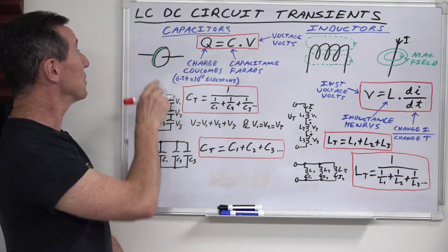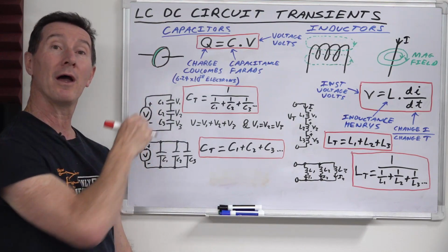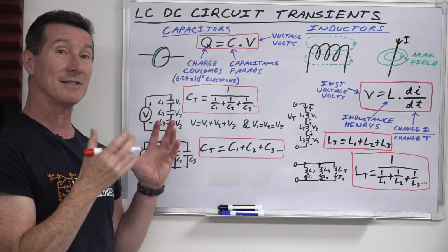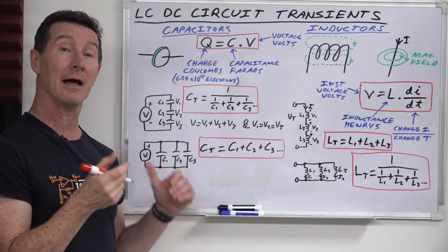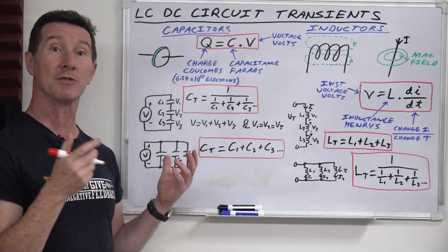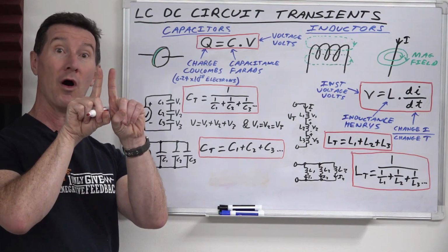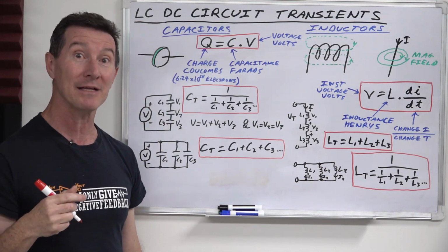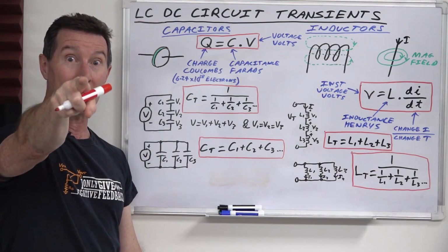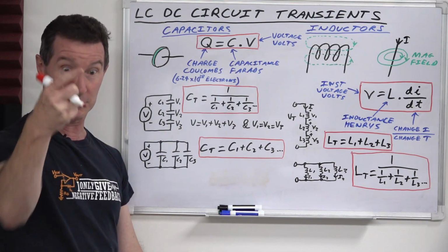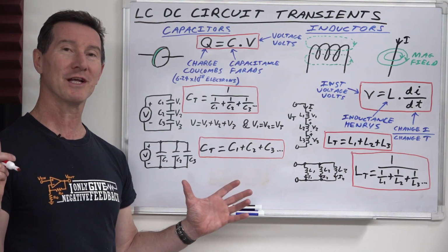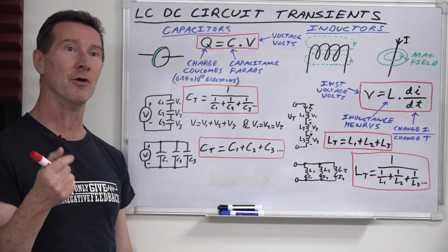Now, a capacitor is just two metal plates separated by a dielectric material, so there's no direct electrical connection. It's essentially an insulator, and that dielectric material can just be air. You can just have two plates or two wires side by side like that, and that's a capacitor. There's capacitance between me and that camera I'm looking at now. You can actually calculate it. In fact, a common tricky exam question might be, what's the capacitance between the Earth and the Moon?